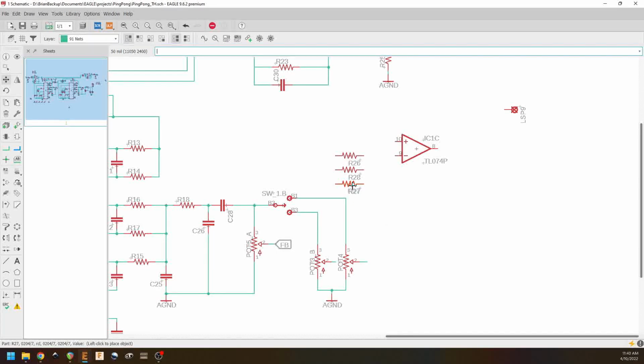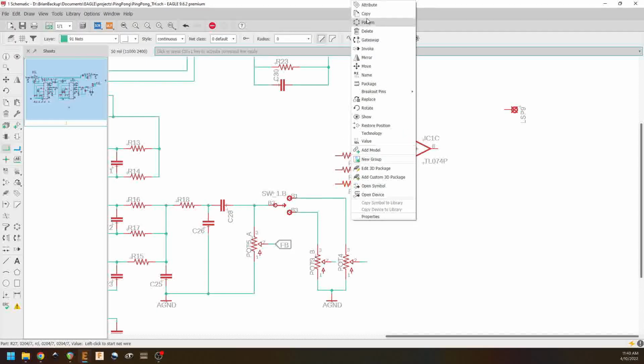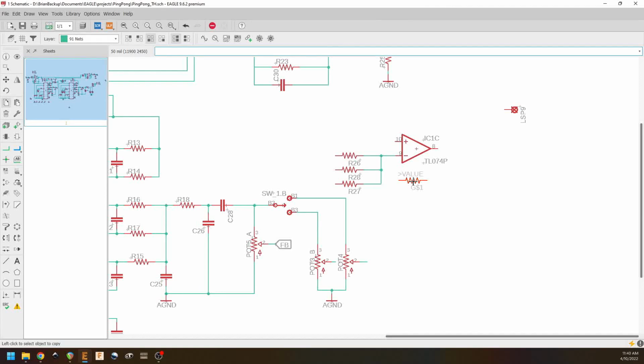When you're doing a summing amplifier on an op amp, it can be really handy to put all of the mixing resistors in an arrangement like this, because then you can look really easily, really quickly at what the values are to get an idea of what the relative signal level is going to be for them. And we need our little capacitor here.